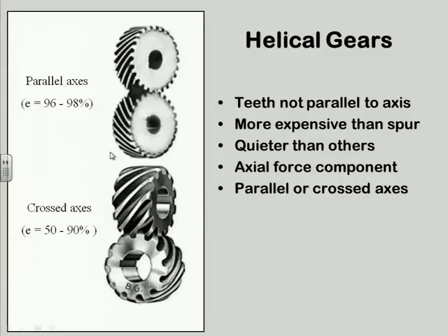But that might make you wonder, how do you shift the ones in forward if you can't take them apart? And the answer is it has something called a synchromesh clutch that actually engages and disengages, and the gears are freewheeling on the shafts. I went through that in some detail in kinematics.